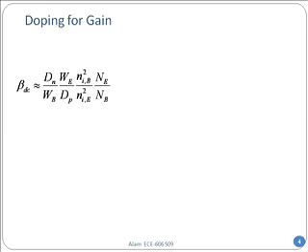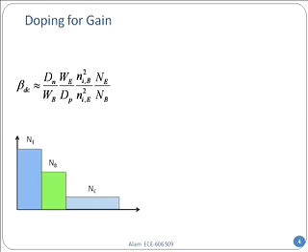And we saw that this gain is related to some intrinsic transistor parameters like the doping of the emitter and the base, the width of the base and the emitter regions, and of course the diffusion coefficient, meaning how fast the electrons go. You see that's in the numerator, D sub n. So if the electron goes fast, that means I have a lot of collector current, and if somehow the holes which are back emitted base current, if that goes slow, then that's a good thing for me. And overall, I will have a great beta DC based on these parameters.